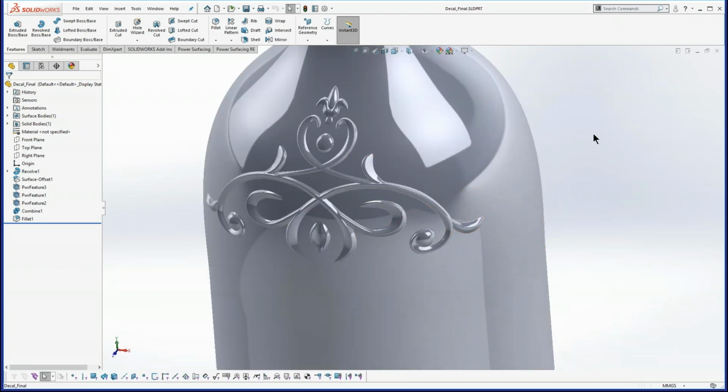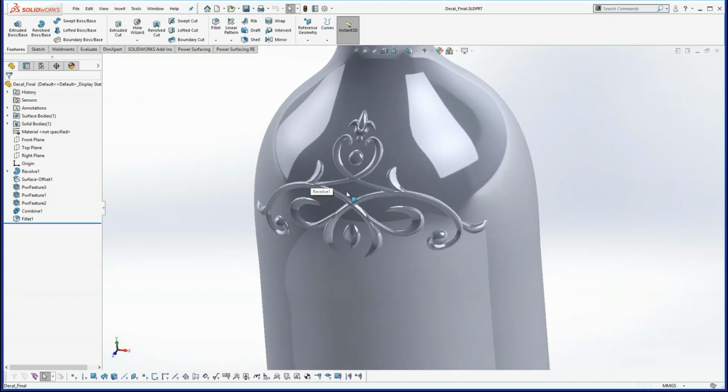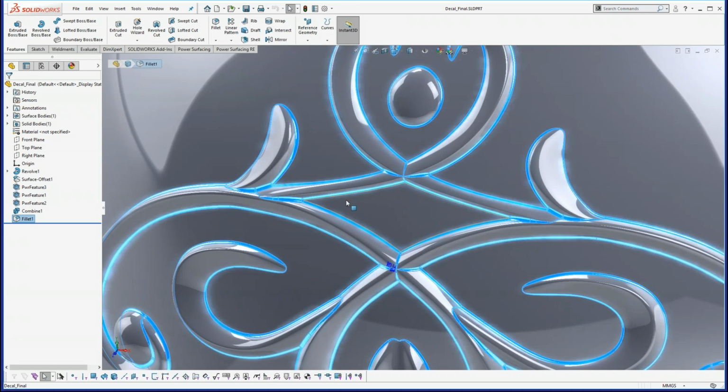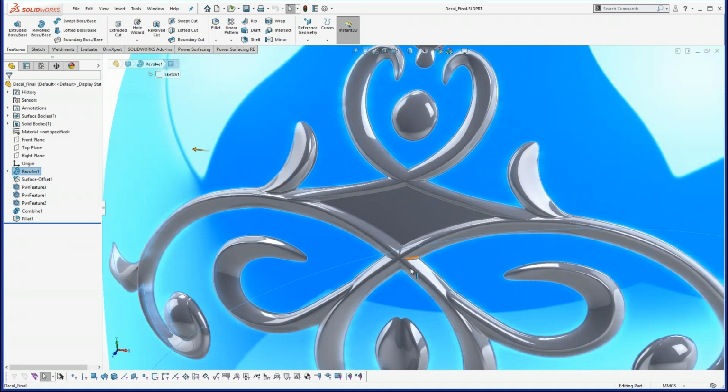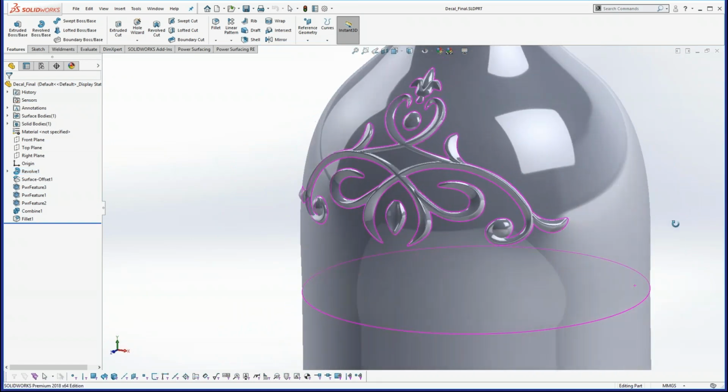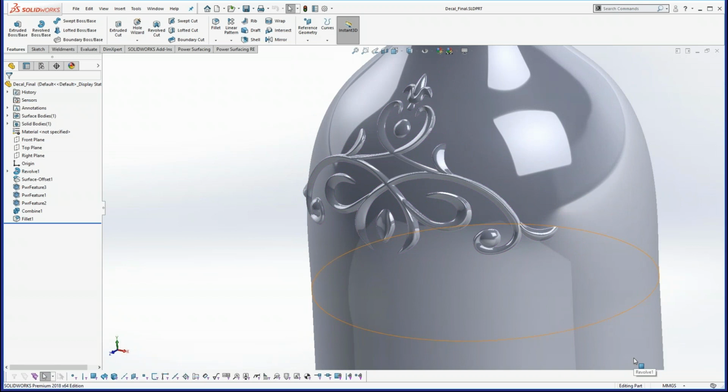And there's a few different ways you can do this. This particular one, I actually extruded them and used combine because I didn't want to have to deal with overlaps, so I thought I'd let SOLIDWORKS do it, and it did a very nice job. And I've even got a little fillet on the bottom bits there. So that was something that some of our customers have been asking for a while, is how do I do an applique sort of thing.